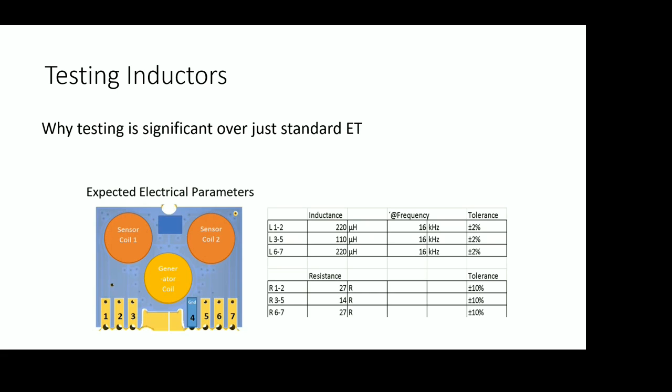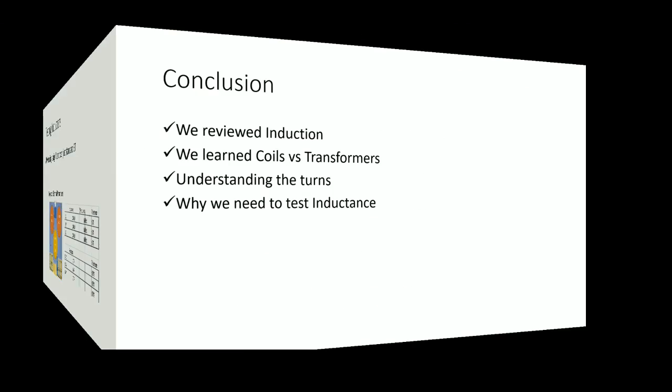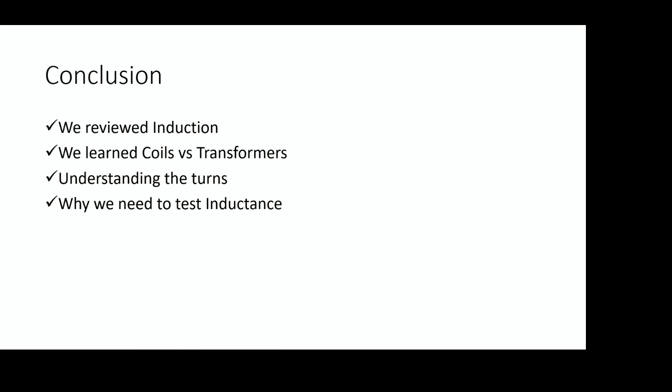Now, it's something you're not going to find with a standard opens and shorts test. So I can't stress enough, like Rick said, why we really need to check inductance for real on the bare board before we go on and add all the expensive components.